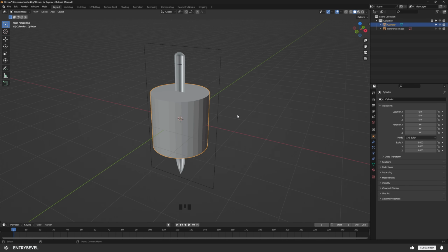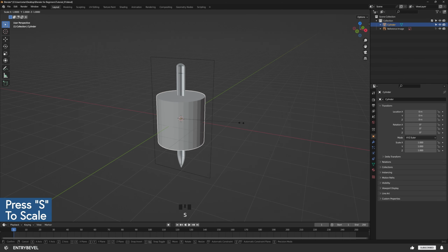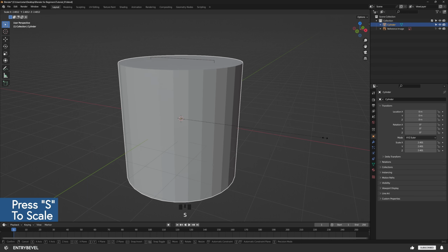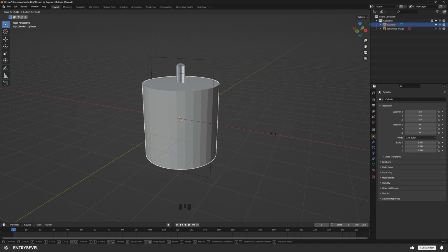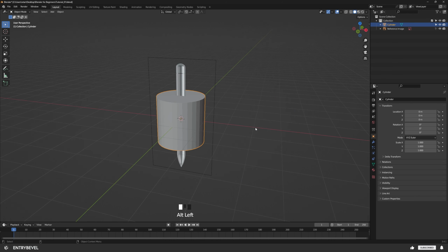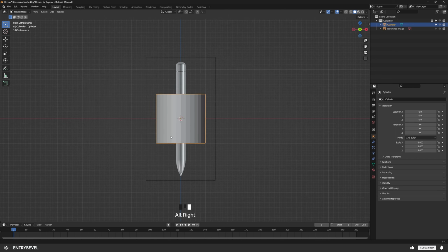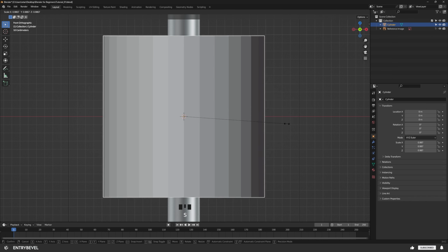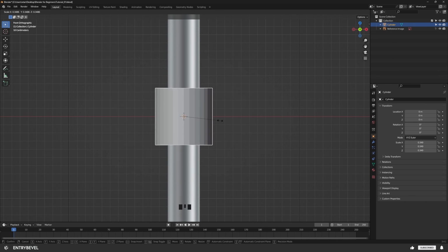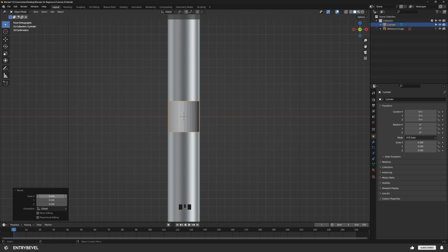In 3D programs, making things bigger or smaller is scaling. And to scale things, you press the S key. As you can see, now we can adjust it as needed. I'm going to press Escape to undo this operation and go back to our front so I can look at it properly. I'm going to press S again to scale it, bring it down, something like that. The scaling that we did, this is the actual mathematical operation. I'm going to just do 0.2. All right, that looks good.